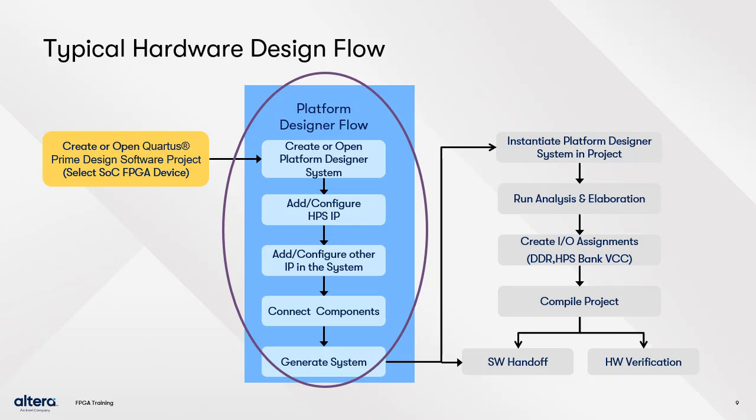Generate the system, which will create simulatable or synthesizable HDL versions of the system depending on the generation options. Software handoffs generated will go to the firmware engineer. From that point, you can functionally simulate or include the generated QSys system in the Quartus Prime project.